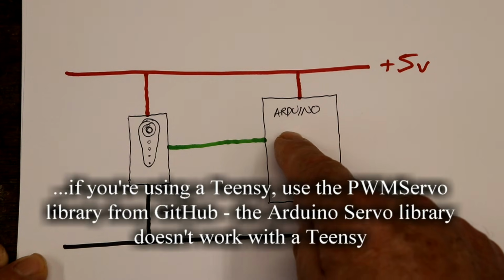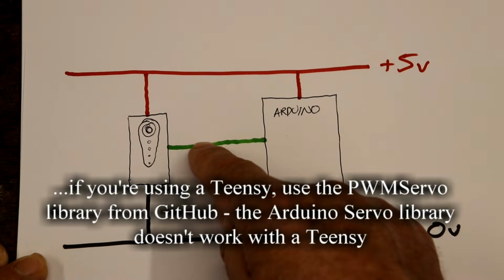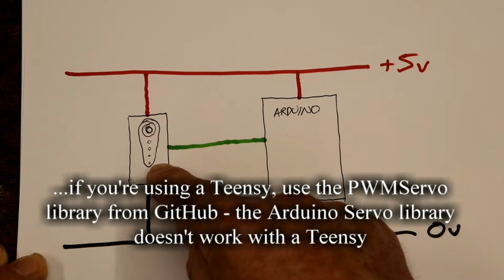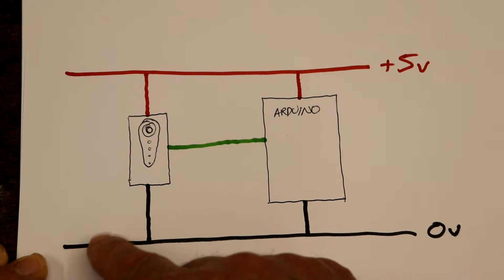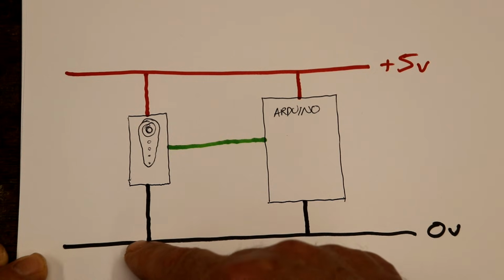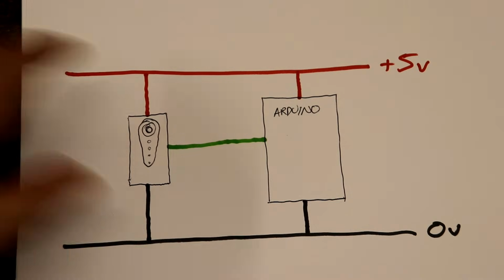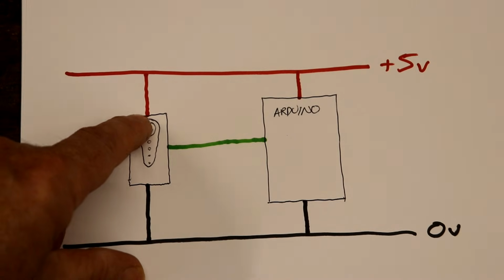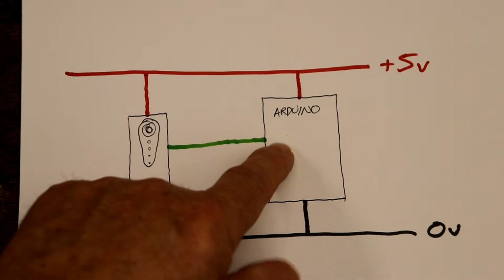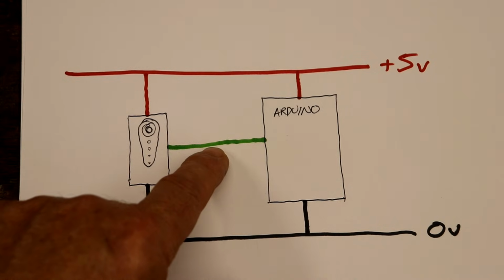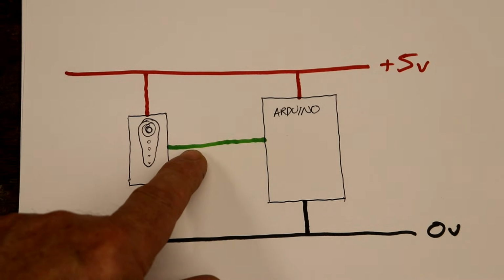So the microprocessor can send out a low current signal to the servo motor, and that signal can find its way back with the common ground or 0 volts. The motor inside that needs lots of current can get whatever it needs from the 5-volt supply. So the only current leaving the Arduino microprocessor is very, very little, probably about 1 or 2 milliamps, which is absolutely fine.